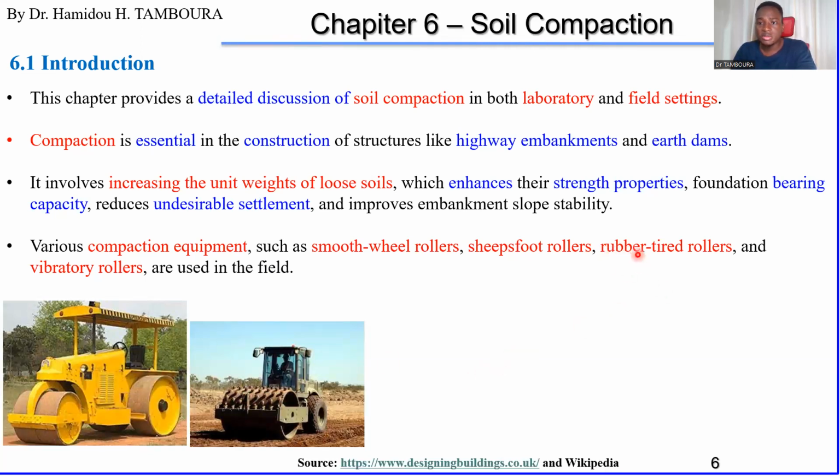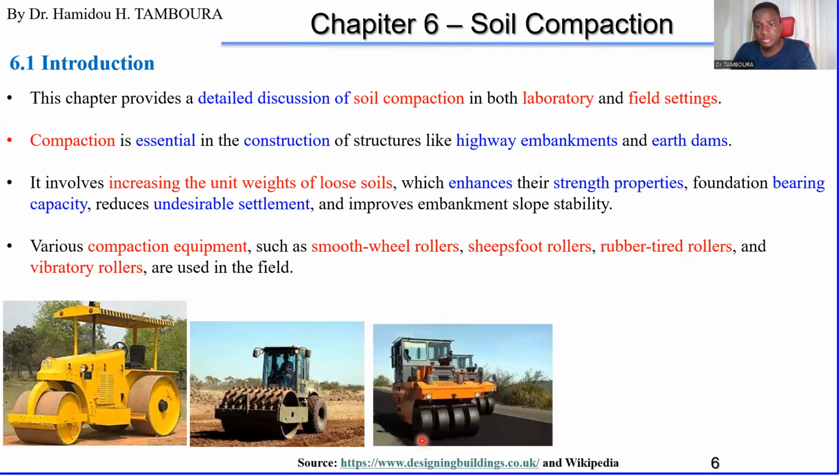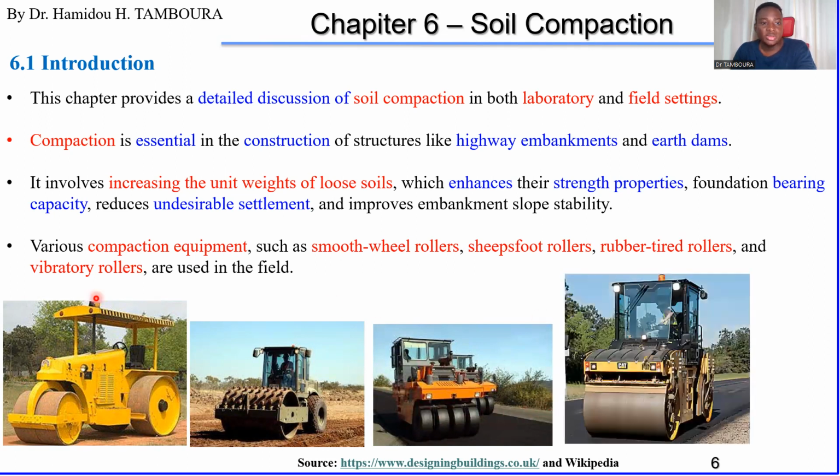Another one is the rubber tire roller. This one, see, just plastic rubber. Another one is the vibratory roller. This one is heavy and is also vibrating. Because of the vibration, the densification can reach deeper parts of the ground.